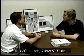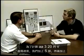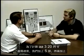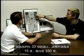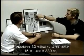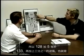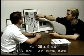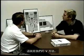Okay. On a 320, well, first of all, we start with the VLS. To calculate V approach on an A320, we add 5 knots and then a third of the headwinds that are entered on this page. So because we're on runway 33 and the mag winds here say 330 degrees at 15, a third of that would be 5 knots. So 128 plus 5 is 133, plus a third of the headwinds, which was 5, which would give us 138 knots. That would be our V approach.